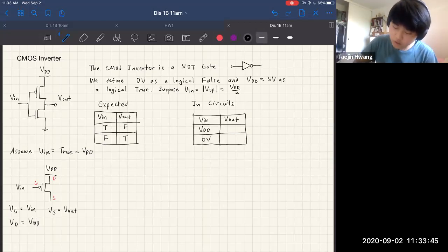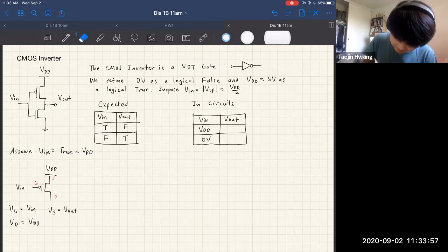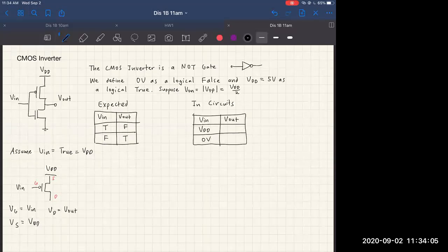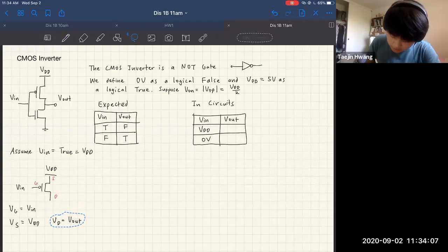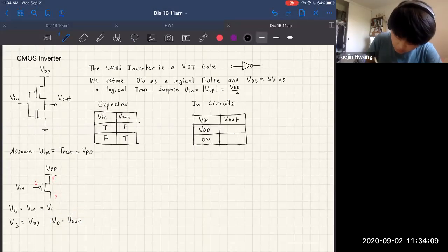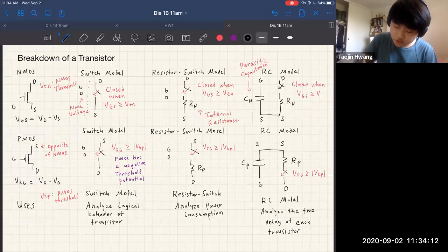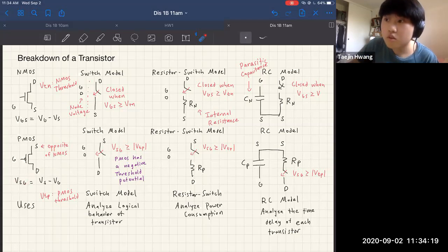And whenever we want to figure out whether this transistor is on or off, this is the source, this is the drain. We want to compare the two values. So this is something you always write on your cheat sheet. You want to check whether V source gate...